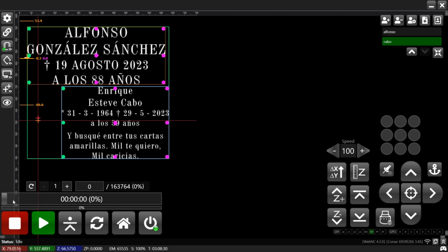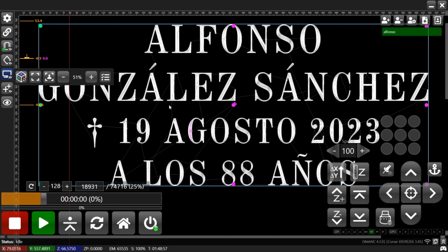We can also resume the operation by choosing where the machine should restart manually. This indicator shows us the number of steps that have been performed. We have selected an increment which length is 0.1 mm. We can select several increments, this way it will be easier to see where we are at. Here we can see where the job will resume after we restart the machine.